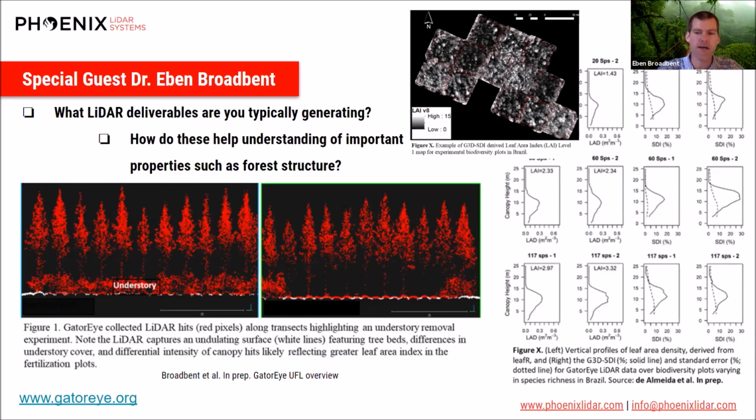In addition to that, we've come up with our own suite of algorithms that the Gator uses to provide custom and one-of-a-kind deliverables. That's something that I've been working heavily on with postdocs and other students of mine. One of the things that we do is retrace every single LiDAR pulse through its entire trajectory from being launched to its impact. And we figure out how many times every single voxel, or volumetric pixel, has been sampled, meaning that a laser has passed through it.